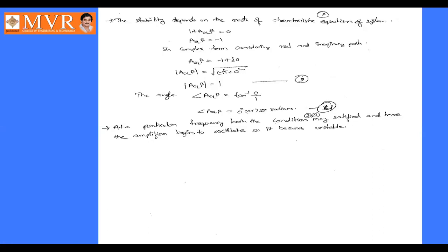In fact, it must act as an amplifier. But here, because of this closed loop, the loop gain becomes unity. When this loop gain becomes unity, the circuit is going to act as an oscillator instead of acting as an amplifier. We consider the op amp as a non-inverting amplifier, but here it is going to act as an oscillator. This is nothing but an unstable condition.